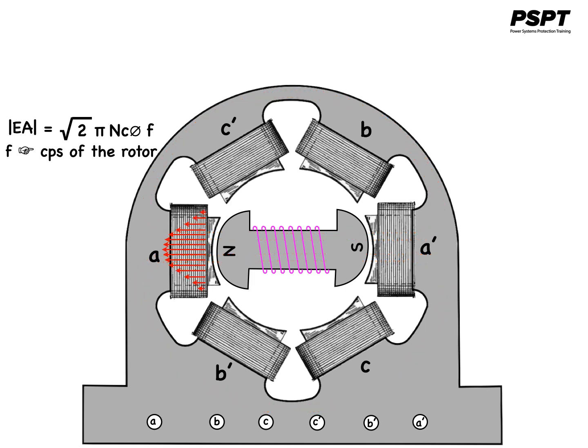Let's unclutter the diagram now by removing the coil coloring, and I'm going to replace the flux lines with a set of flux phasors or vectors that would be appearing in the air gap. You can see that the flux lines vary sinusoidally over the face of the pole of the rotor. Remember, these flux lines would go around the perimeter of the stator and return through a primed coil into the rotor south pole.